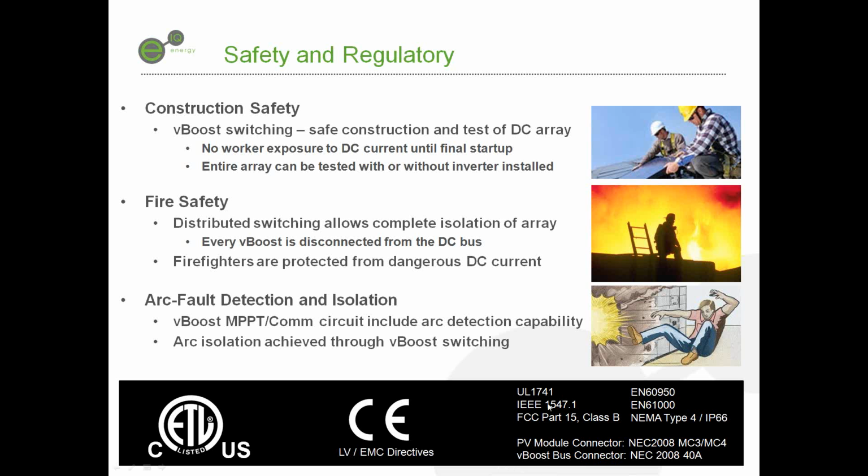The other is fire safety, because just the same way that during construction we have a safety mechanism built in not to allow that voltage to get onto the bus. The same thing during a fire. If there's an emergency at the location and emergency workers need to get onto the building, the system can be shut down so that no high, potentially life-threatening voltage is present anywhere within the array, because as soon as the boxes turn off, the vBoost units themselves, the most voltage that's going to be present is the voltage potential of a single module, and then it will only be present at the module. So we're going to greatly reduce the risk to those emergency personnel.